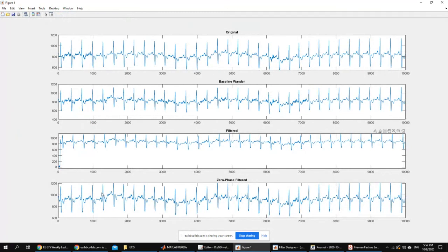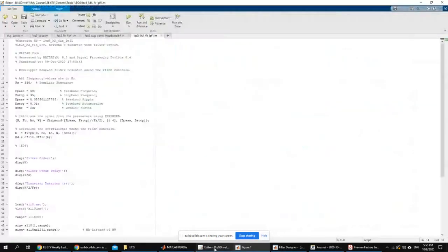It looks better. Look at this one here, for example, and compare it to this one here. As I told you before, whenever you have high frequency noise, it would look like a thicker line. Actually, this is thicker than this here. So basically, we're improving now. Do you see any distortion in the ECG signal itself? I actually still see the ECG signal okay. It doesn't really have any problems. The QRS, which has the high frequency in the ECG, still looks very sharp. Okay, let's try it a little bit further. 20, 25.